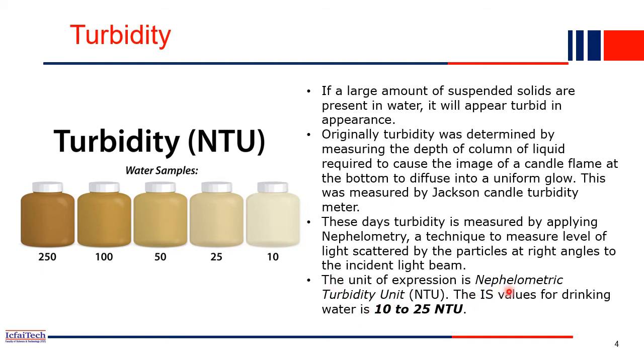So nowadays we are using the nephelometric turbidity unit, NTU. This NTU is the nephelometric turbidity unit. It follows similar physics as I mentioned. Light is passed through these bottles, and depending on how much mud or solid is present, dissolved in the water, that much light will be absorbed and the remaining will be recorded at the bottom. So based on how much light has been absorbed by the material, this NTU unit will give the value.